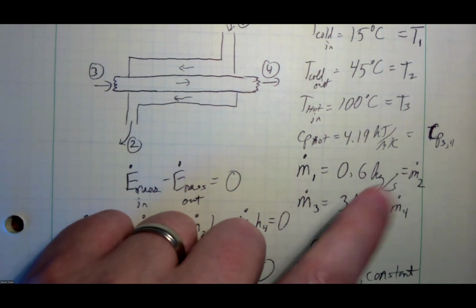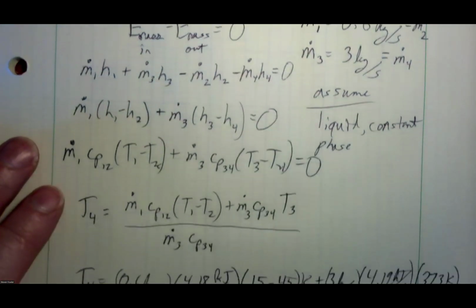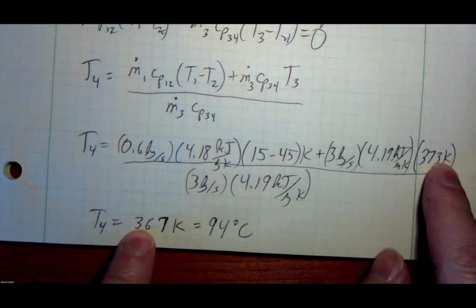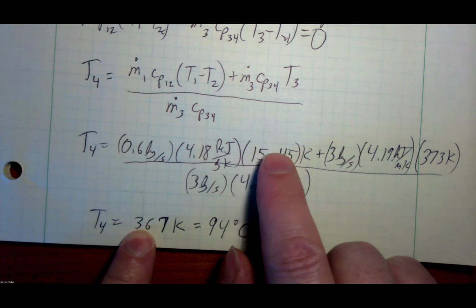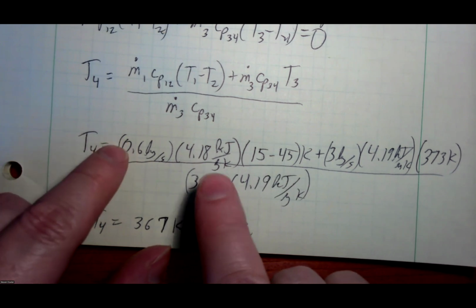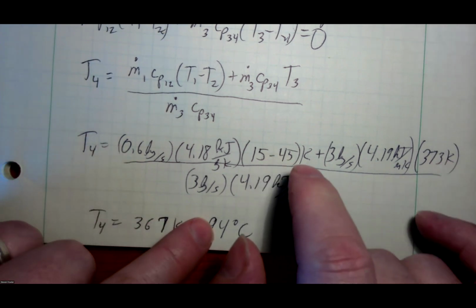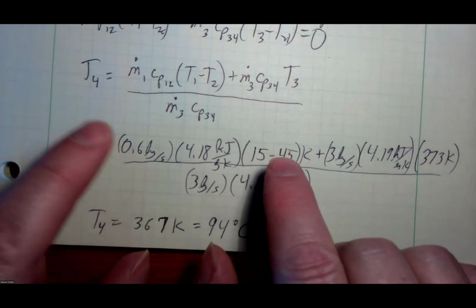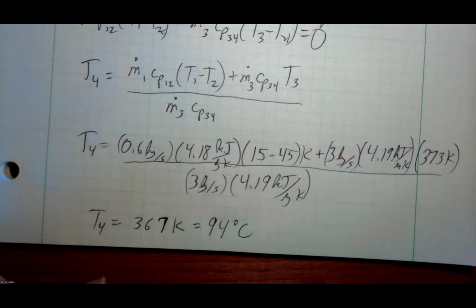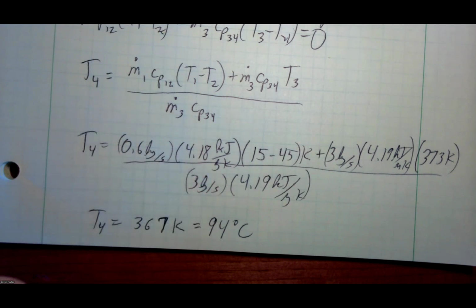I have 5 times as much mass flow for the hot stream, so I should experience about 1/5 of the temperature change. So it's a 6-degree difference for the hot stream as compared to a 30-degree difference for the cold stream because I have 5 times the difference, right? 30 is 1/6 of the difference here. So I'm sorry, 1/5 of, right? So you've got 1/5 of the difference between the two streams because I've got 5 times as much mass flowing through the hot stream. That's the reason.